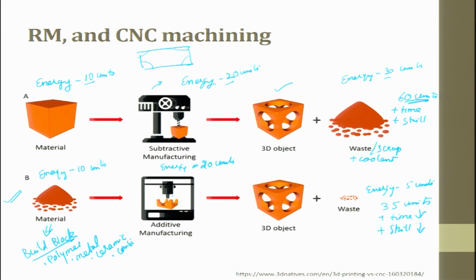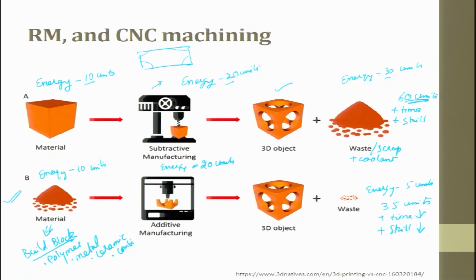Because when you start doing this rapid prototyping part, the strength plays a very important role, finish plays a very important role. So, the strength and finish can be decided by the orientation of the part, which also can be given by CAD today. It gives you multiple options, you have to pick which one, which will also tell you if you do the orientation like this, this is what is the time going to take. So, all these things you yourself can optimize and then start firing the machine. So, you look at it. So, this is the difference between ordinary subtractive manufacturing and this is rapid manufacturing.